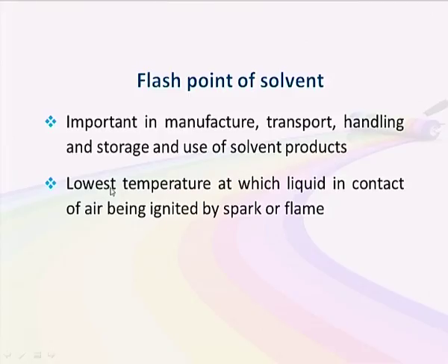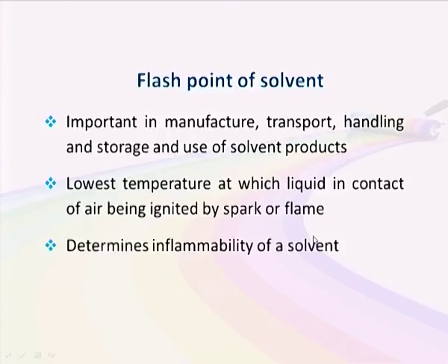Now what is the flash point? Flash point is the lowest temperature at which a liquid in contact of air can be ignited by spark or flame. So this basically decides the inflammability of a solvent. If flash point is low, that solvent will easily catch fire. So it will not be safe to transport or to store or to handle.